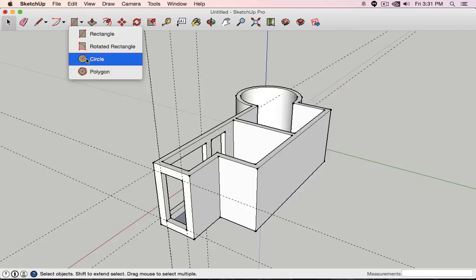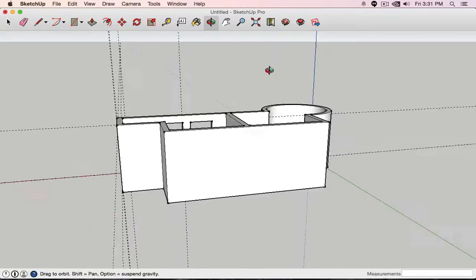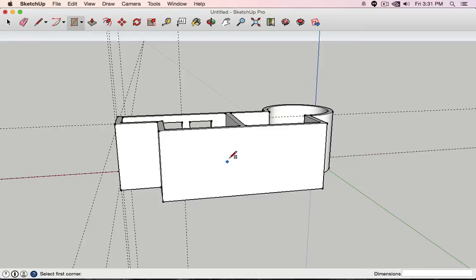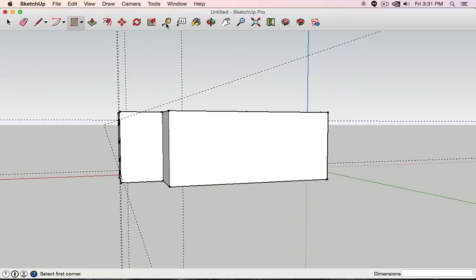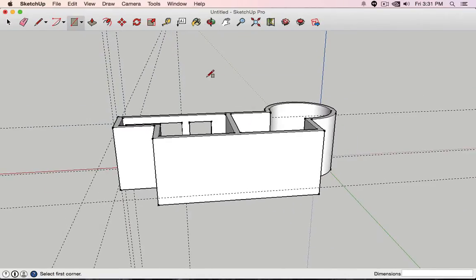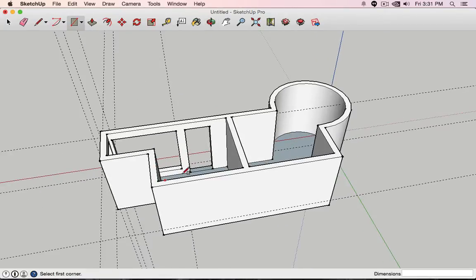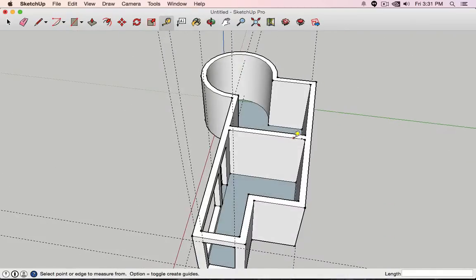Obviously windows could also have a circular shape. But let's say we would like on the back create a window that is rectangular and has kind of a Roman style from the top. So 1 foot, so keep it all the same. And for example now from the inner wall, I would like to have 1 foot. So check out this one. Here I create a guideline and I create a guideline. You see I'm running the inner edges to the outside wall.